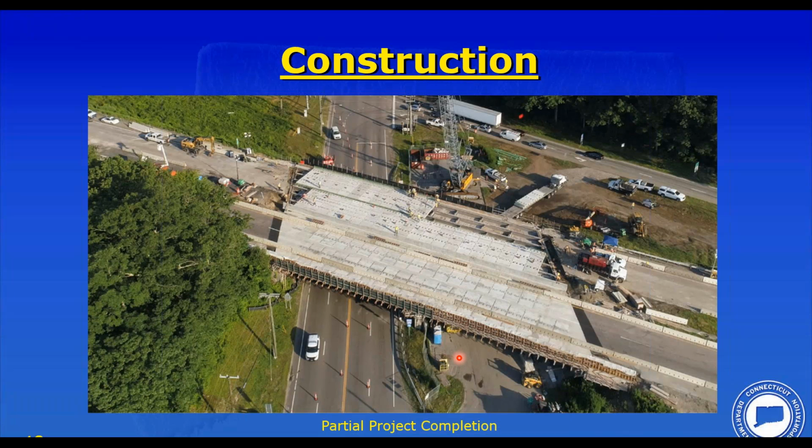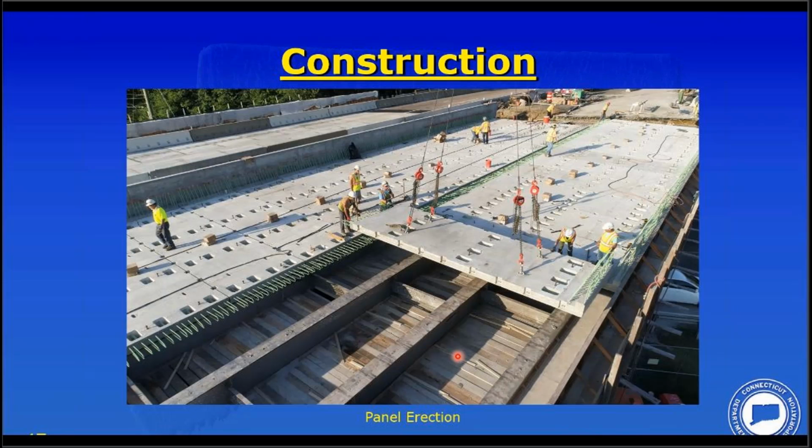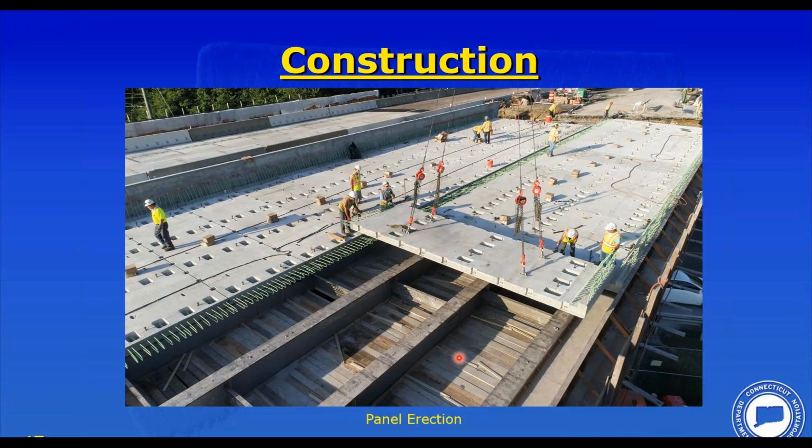Yeah, usually the top flanges are bare, but any project that has lead paint in it has specifications that address the concerns the contractor needs to follow with that. And this did include full painting, so this would have been abrasive blast cleaning and removal of all lead paint. So I'm sure this was adequately covered in the project.